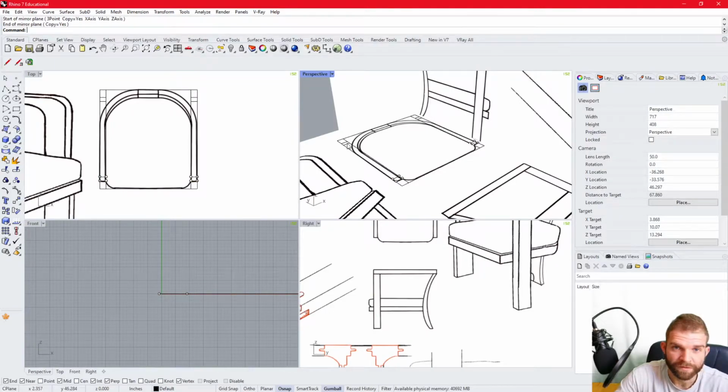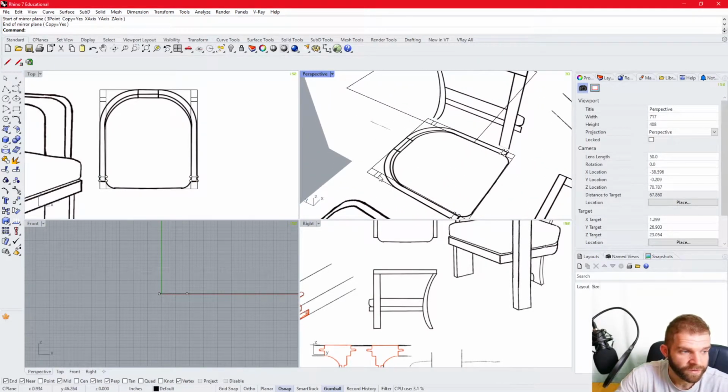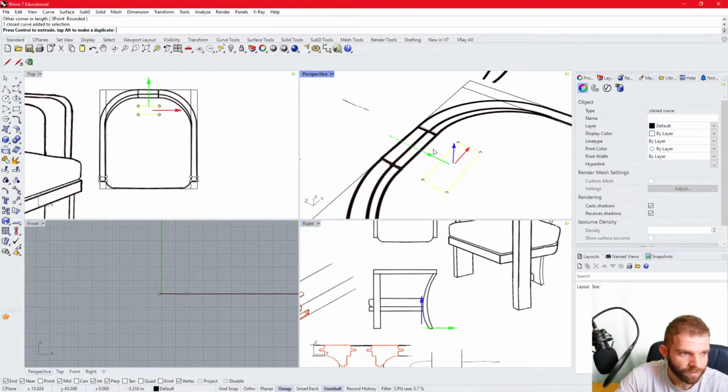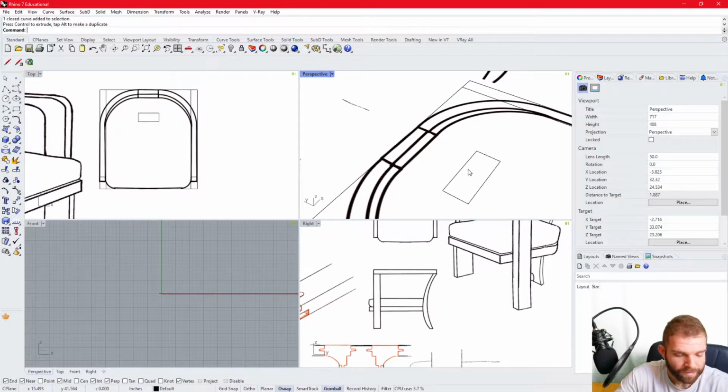And that allows me to place the feet back. Although in this case, this would be if you were making a chair with 4 legs, which is something I standardly do, but in this case, I have only one in the back. So for the one in the back, I'm going to more or less just draw out a rectangle for that shape. Then I'm actually going to use the gumball to drag it out here and use the move command to then grab it from the midpoint and place it on the midpoint of the other line segment.